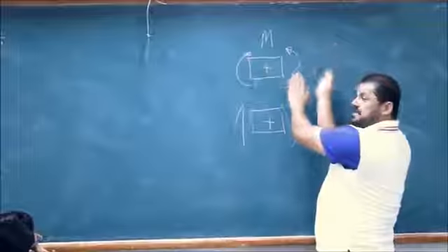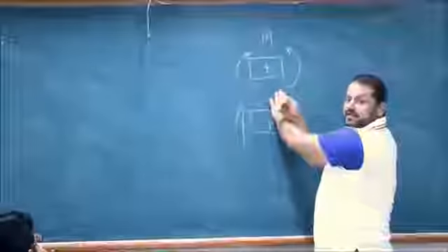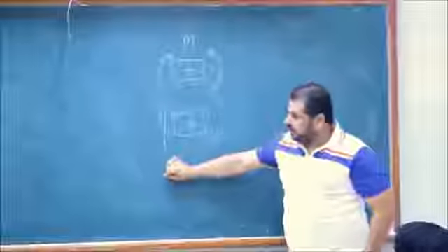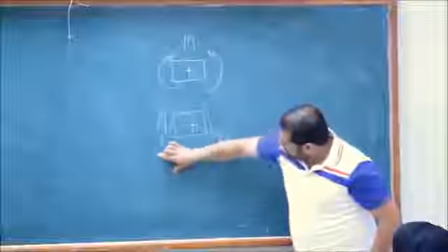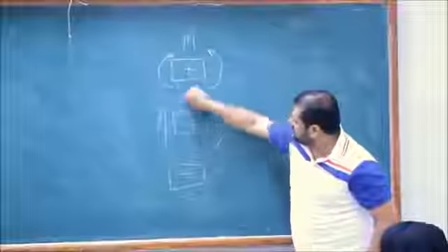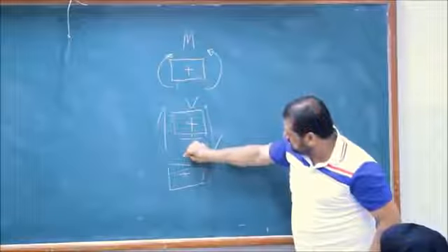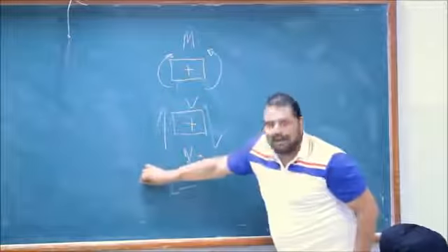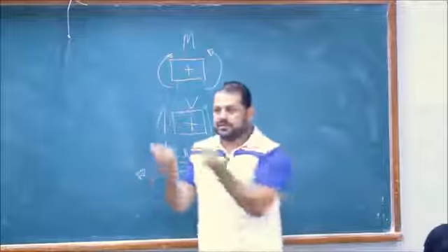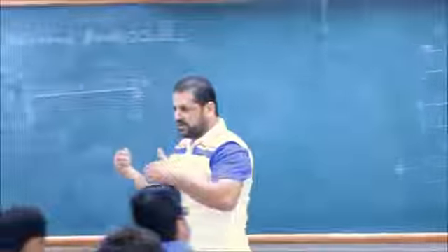If I'm looking at the right-hand side and it's like this, it's negative. Otherwise, negative. This is how you evaluate the internal forces. Whether this is shear, V, and this is N, or normal: up, out of the cross section, tension; in a cross section, compression.